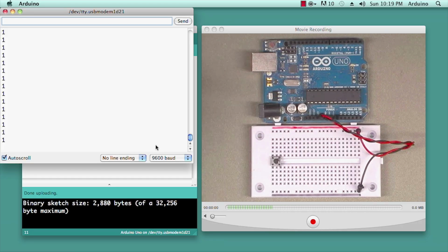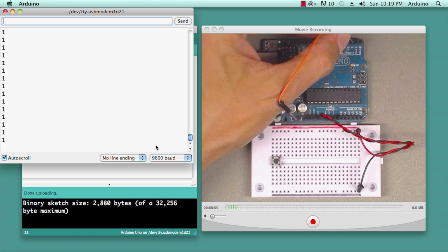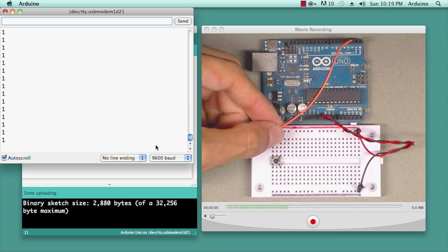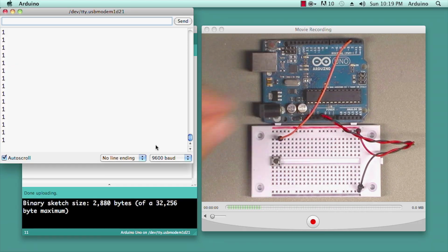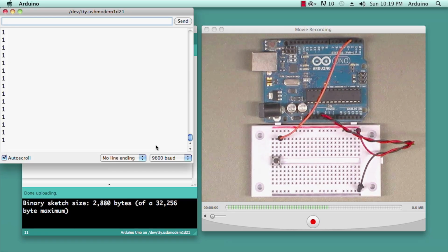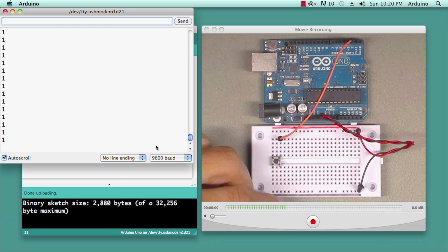So now let's put back in our signal wire. So we'll go back into pin number 2. And we'll come over here and we'll go into the right-hand position at the top. So now we're connected to the right side of the switch all the way through. And if we look back at our circuit diagram, you'll see the signal cable, and it connects to one side of the switch. And then on that same point electrically, which means anywhere in this right-hand column, top or bottom, we need to make a connection through a resistor to ground.